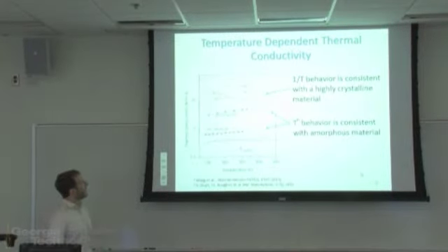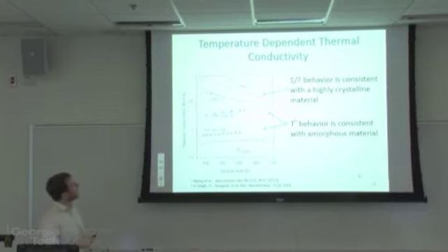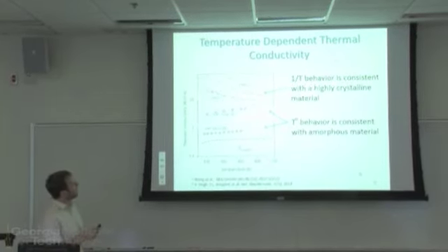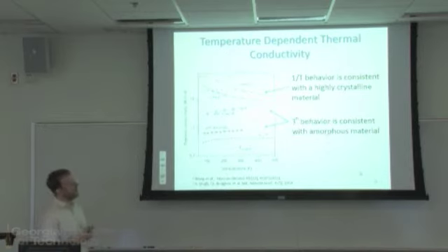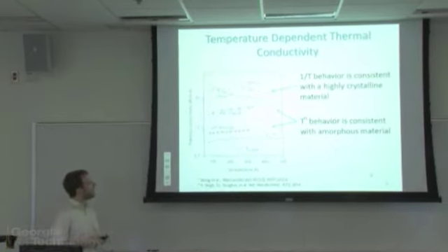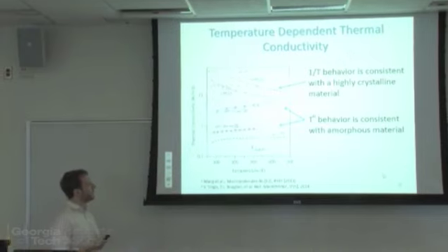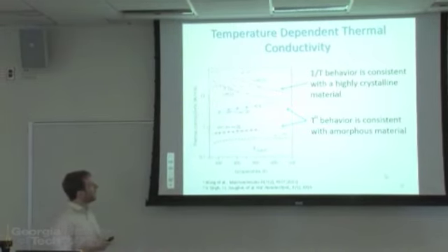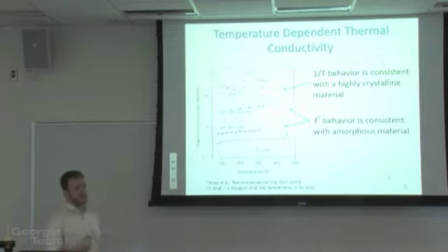Which one? Well, actually, that was polyethylene. So I guess this is polyethylene. They also did Kevlar, but I guess I didn't put it on this plot. But they looked at it. It does have a similar trend in temperature dependence. They looked at about 5 or 6 different commercially available drawn fibers, nylon fibers, I think, and they found pretty much all of them, because they were so stretched, showed a high degree of crystallinity and high conductivity like this.